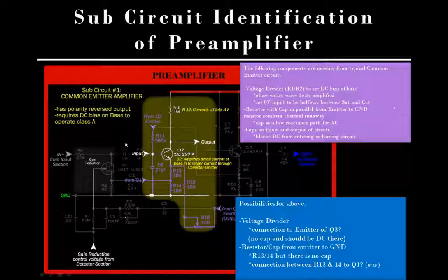There is a capacitor here earlier in the circuit. So if you want to think about that being C1, you could. But it's really not part of this subcircuit. If you identified that as the typical C1, I'd be okay with it. I don't see it that way in this particular circuit. So we need some DC getting here to bias the base, since R1 and R2 aren't there.